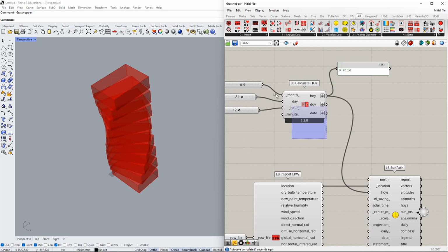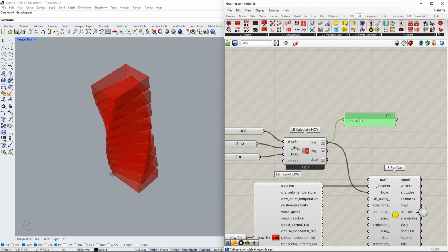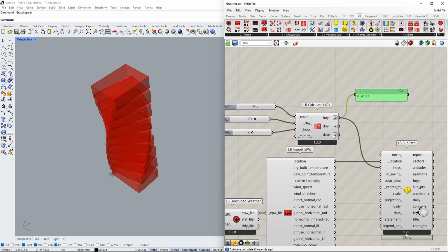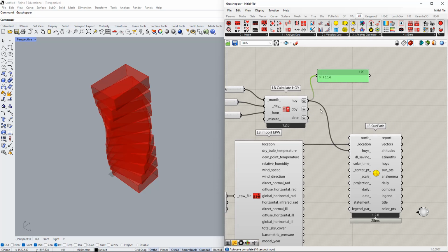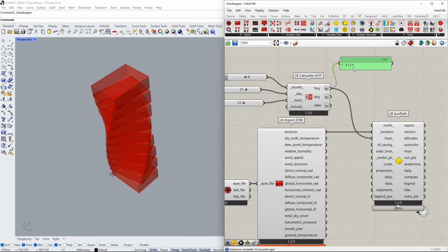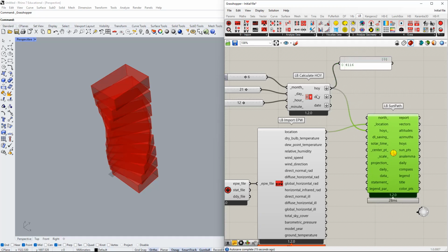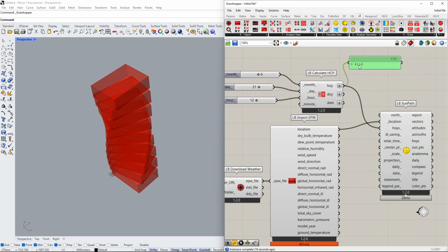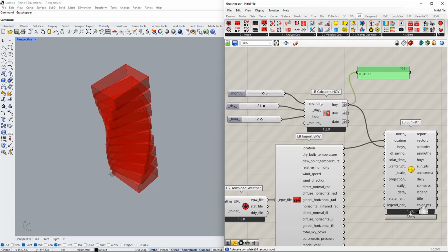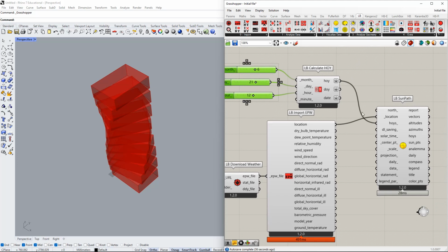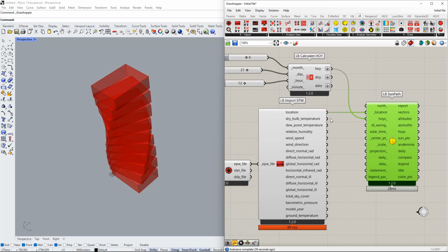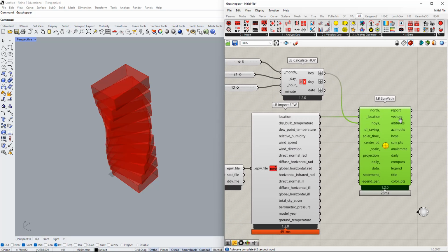That's something different in Ladybug than the usual Grasshopper. Ladybug is going to use its own information, its own way to read information. Like in this case, this number, the Ladybug component knows that the number goes in there. So for you, it's not about matching that number, but matching the names of the components. But still keep in mind that the people creating Ladybug are using their own numbers. They still follow the same logic, connecting data from left to right and making sure that the index plugs in correctly.